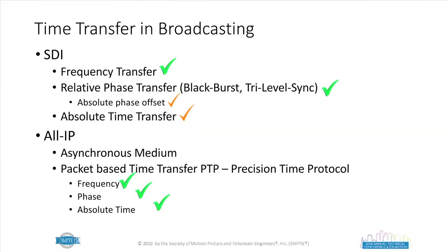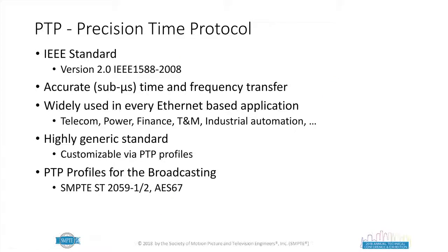From a time transfer point of view, and again, Paul's explained a lot of this in detail, so I won't cover it more than is needed. We have frequency transfer with SDI. We've got relative phase transfer through black and burst, tri-level sync. We have in an IP system an asynchronous medium, obviously, as it's been explained. We've got PTP 1588. We can carry the phase, the absolute time, and, well, the frequency, the absolute time, about phase, we can have a discussion.